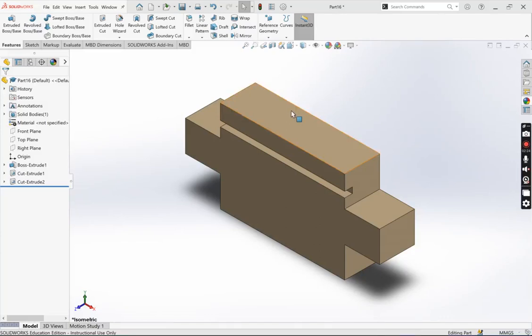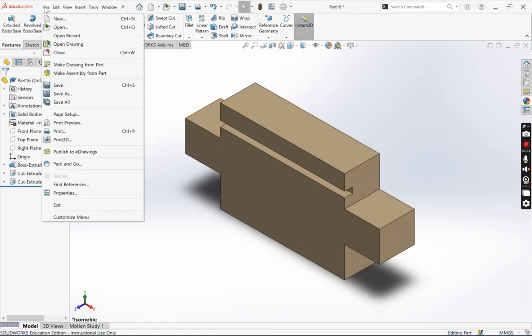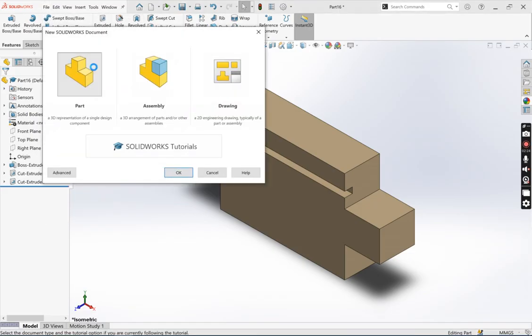We're going to design up the first part of our box. So you can see here's the end piece of the box, the small piece. You can see the 4 cubes removed from the edges, or the corners of that box, and the rebate that's been cut out for the lid to be housed. So we're going to start off with File, New and Part.